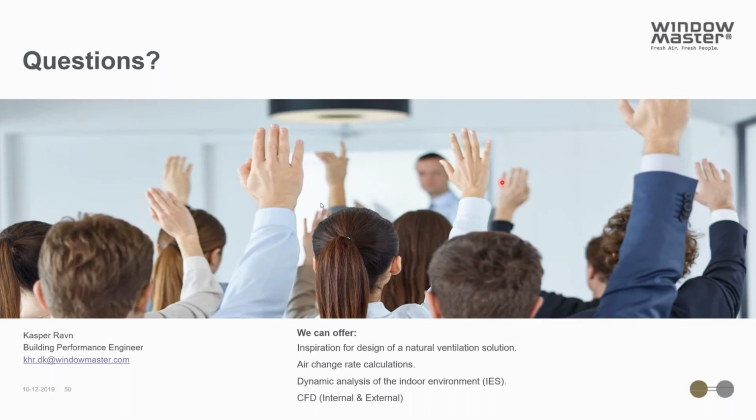As I mentioned before, you can have cases in high performance buildings where you have a surplus of heat even in very cold conditions. In this scenario, if designed correctly, you can use natural ventilation, but then you would deactivate the mechanical system. So that's the whole point. In most cases, in that type of mixed mode system, you would use these two systems independently.